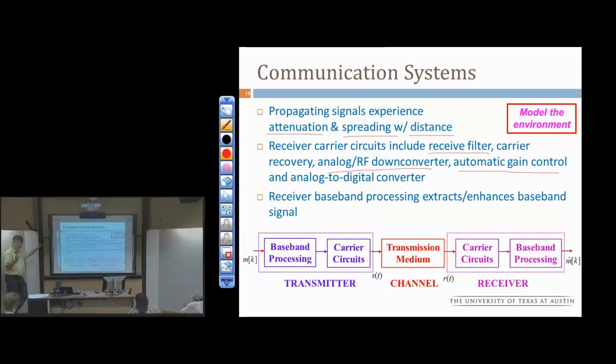Okay, so for the symbol rate, we tend to lock onto half the symbol rate. And for the carrier frequency, we just lock on directly to that carrier. That carrier is present. So they both serve the same purpose, but because of the way the signals are being transmitted, we have to do it slightly differently. Well, they're very different frequency ranges, typically, right?